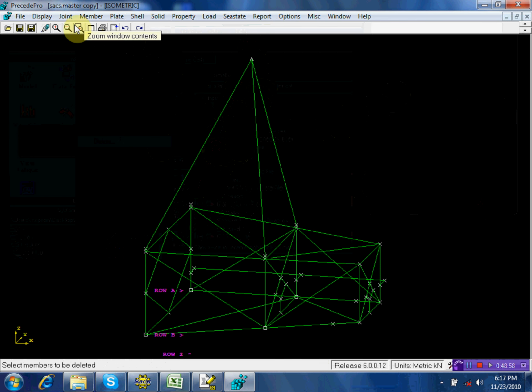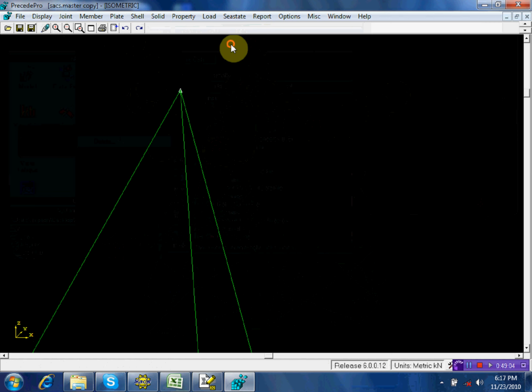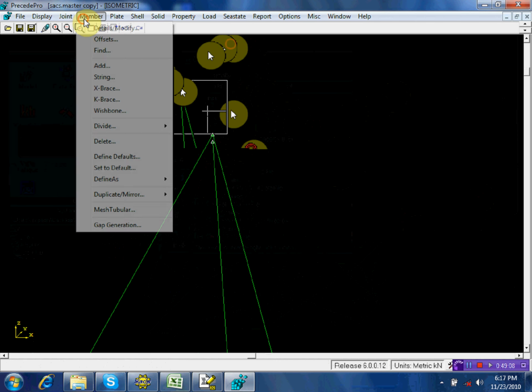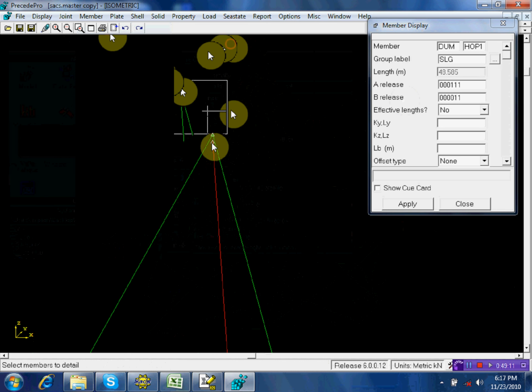No skew effect, meaning to say, all my loads here, or my point, should not be on dummy but on hook. Loadings will be changed. No skew effect. It's only COG shift plus gravity only. Why no skew effect? Skew effect will be used only for 4 slings. With 3 slings or 2 slings, there is no skew effect, no misalignment on that. Usually 4 only. So that's the explanation.